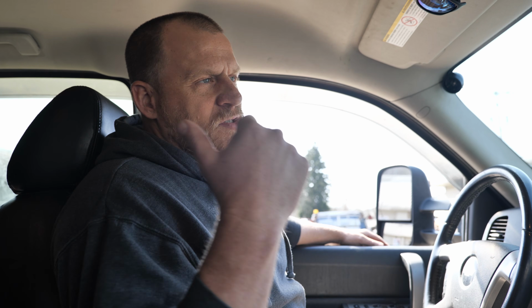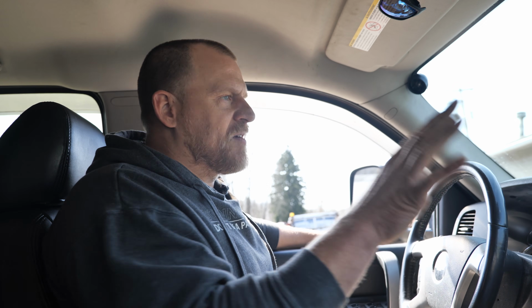So one more piece, I was just talking to Pete. I wish I would have recorded this because it was really good to emphasize you can't change parts based on a code. Here's what we know about this truck, what it doesn't need. It does not need both oxygen sensors. We had 2 codes for that. It does not need a fuel rail pressure sensor. We had 2 codes for that one. It does not need a MAP sensor. None of those. Doesn't need any of that. I thought that was important to add in this process. You can't change parts based on a code.